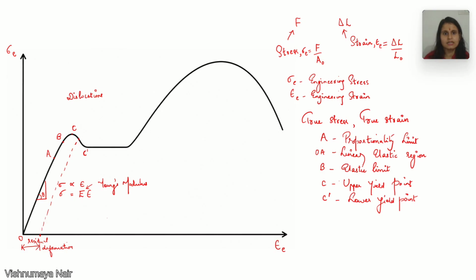In steel, the interstitial atoms like carbon, nitrogen diffuse to the regions near these dislocations and they cluster around the dislocation, forming something known as Cottrell atmosphere. So these interstitial atoms form Cottrell atmosphere around the dislocations and they pin the dislocations. They hinder the movement of dislocation.